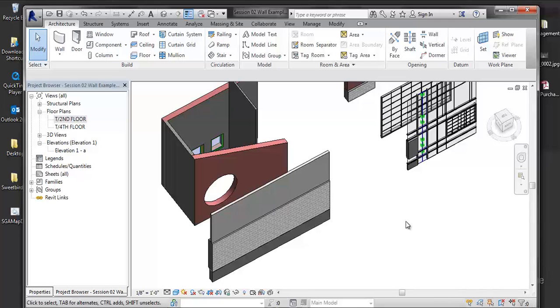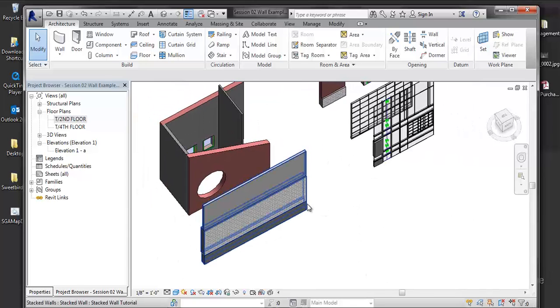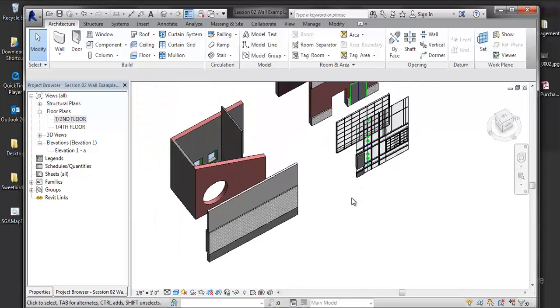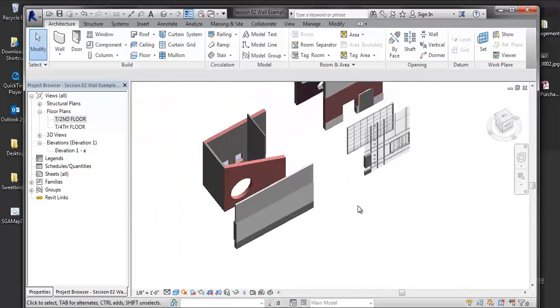Neither do I. Design vocabulary, but I think in cases where you have consistent horizontal bands, stacked walls are appropriate. Where you have variable geometry, doing them as separate walls might be more appropriate. So I think it depends on what the intent is. Stacked walls, the way they're managed in Revit, are really meant to be horizontal, driven off of levels, driven off of horizontal planes.